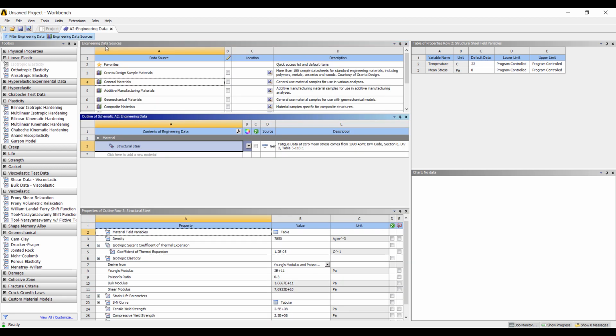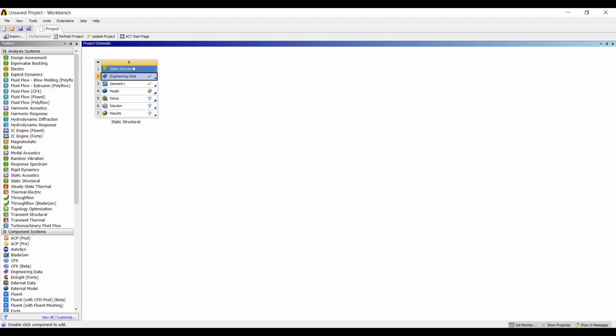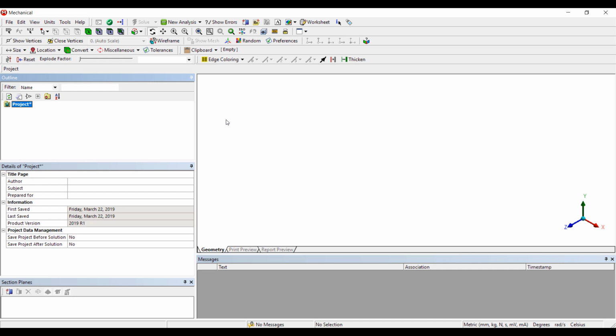So first we're going to add in a material. We'll use polyethylene, so we have a plastic box, and in this box we want to make sure that it's sealed, and we want to fasten it with a couple of bolts. Obviously how well the box is sealed depends on the amount of bolt pretension you have, and I'll show you some quick ways to set up bolt pretension and this type of nonlinear contact analysis using ANSYS Workbench Mechanical.